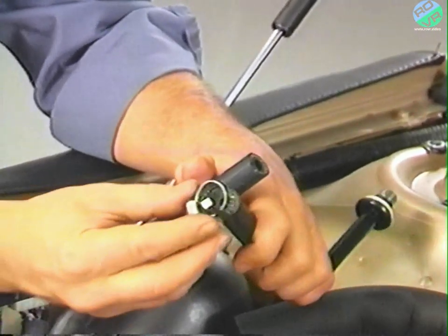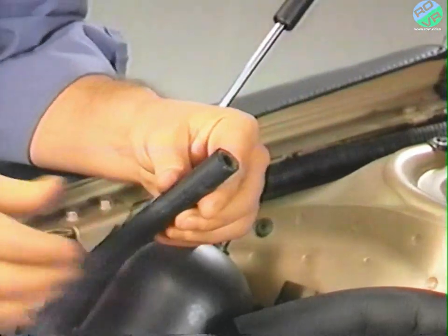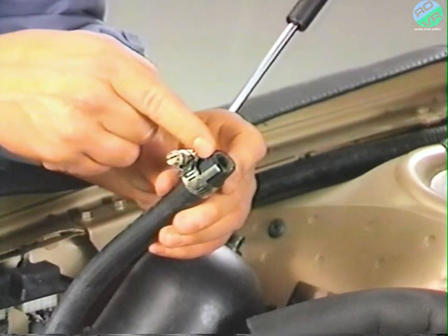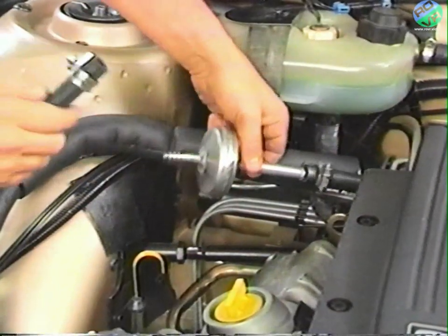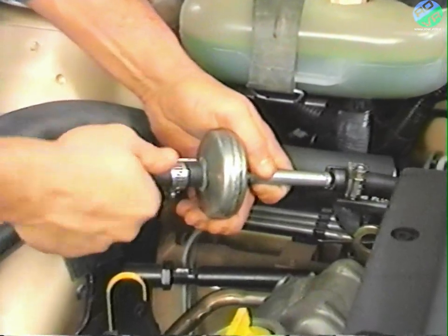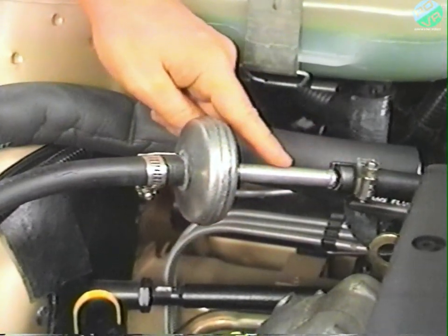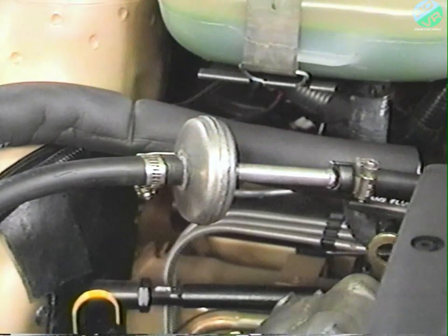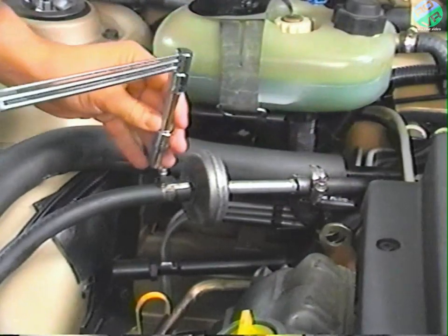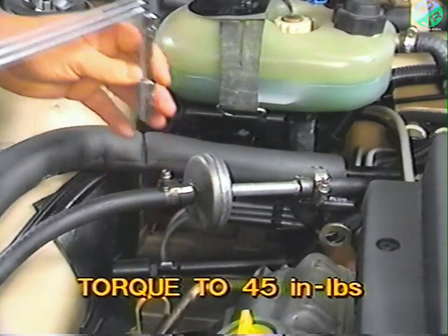Be sure to cut the hose ends square and make sure no burrs or shavings remain that could contaminate the system. Next, slide the clamps from the orifice tube filter kit on the hose ends until the spacer bar ends rest against the hose ends. Then, force the ends of the orifice tube filter into each hose until the filter shoulders touch the hose ends. Make sure the orifice tube side of the assembly is closest to the evaporator. After making sure the spacer ends still rest against the hose ends, tighten the hose clamps to 45-inch pounds.